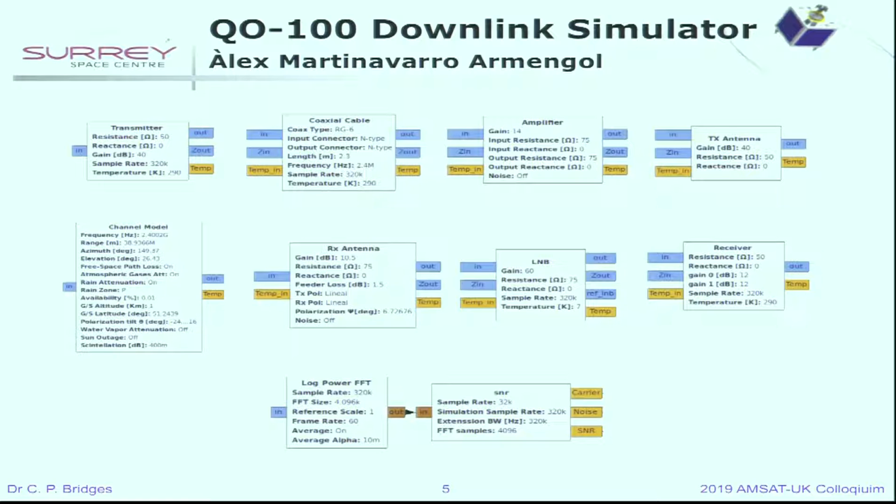So building mobile communication simulations and being able to see, does this work, but in a much more dynamic environment. If your noise floor changes, if you want to test things sweeping in and out of your signal, you're not doing that on an Excel sheet. Okay? You can do these things in GNU Radio. And so we came up with a whole new series of blocks with the transmitter adding in resistance, reactance, the actual noise temperatures of each of these systems.